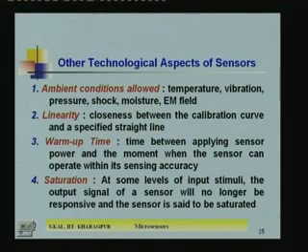After switching on, how much time it takes to sense the input stimulus or to change the output with respect to the input, that is known as the warm up time. How much time it takes for full functioning. So, that means the time between applying sensor power and the moment when the sensor can operate within its sensing accuracy, that is known as the warm up time.